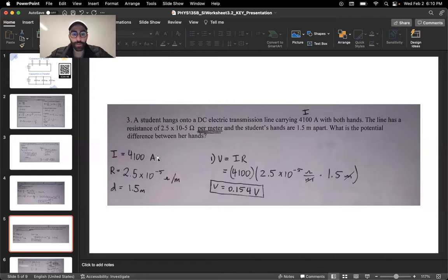So here we have a current, we have a resistance, and we have some length. Important to note here is they didn't just give us the resistance, they gave us the resistance per unit length, that being meters. So when we solve, we're going to need to cancel out those meters. And you can just see how, mathematically, we just plug in that distance right here and end up canceling out the meters. But that actually lets us treat this as that value, but in ohms, not as ohms over meter. So again, we're going to use Ohm's law, and we're just going to solve it out for V.